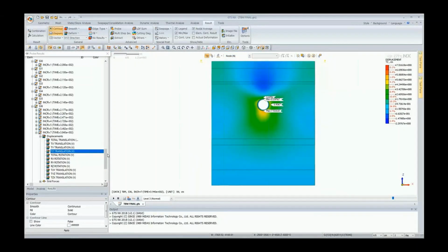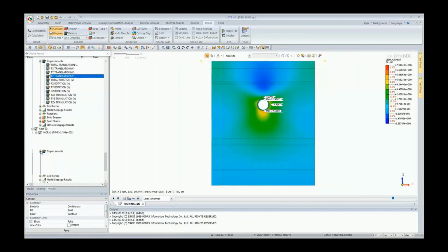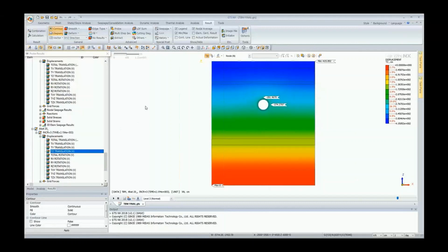And so now the last thing is let's verify the vertical displacements during the pore pressure reduction. Now this case was simulating conditions in the Valley of Mexico City, which is very soft clay, and there's a high settlement due to the pore pressure reduction over time. So we'll see here, I'm going to click at the top of the model and around the tunnel excavation, and change my units to meters.